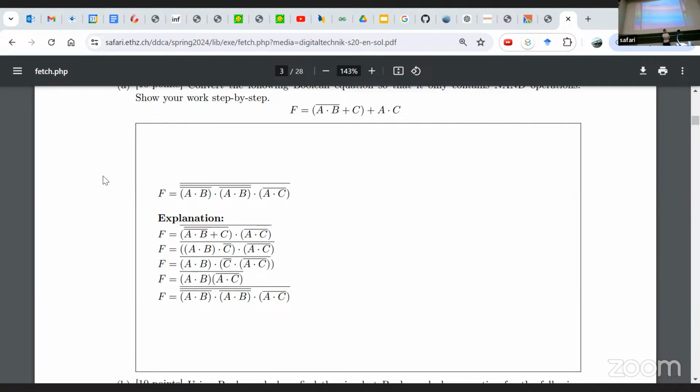So it's trying to capture its input, and all of a sudden the new input comes. And because it needs the hold time, where the previous input stays stable there, if a new input replaces it before the hold time is over, we have a problem. And those two things you have to know. For a simple thing, we will ask them one way or the other, in combination, in something a little bit creative, a little bit less creative, but they will come, I think.